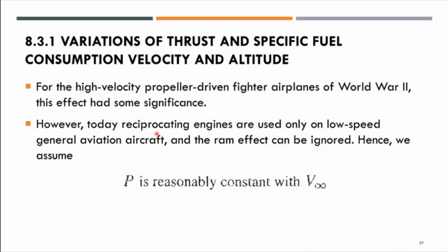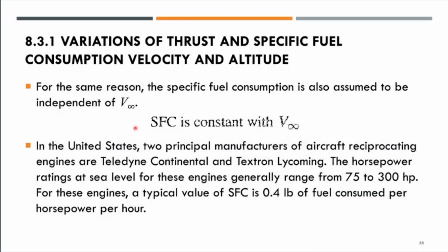So for the high velocity propeller driven fighter airplane, in the case of World War II, this effect had some significance. However, today, reciprocating engines are used only on low speed general aviation aircraft, and the ram effect can also be ignored. So we assume the shaft power P is reasonably constant with the free-stream velocity V infinity. Okay? So for the same reason, the specific fuel consumption SFC is also assumed to be independent of the free-stream